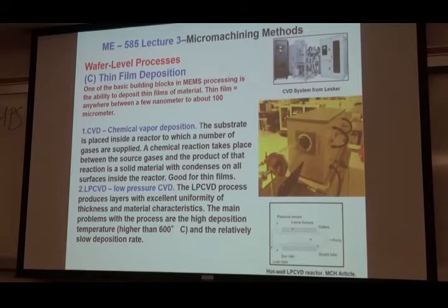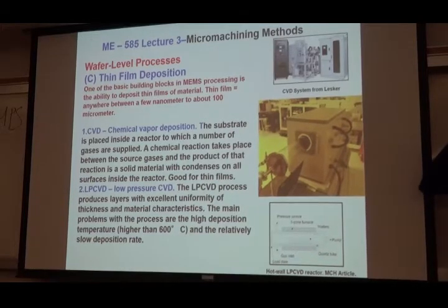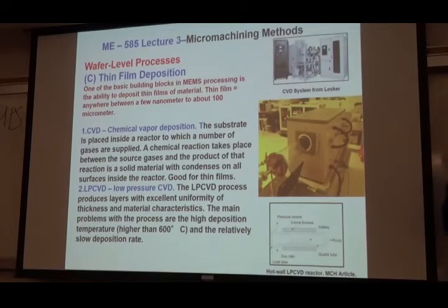Now, there's a material called graphene. That comes to that. So for the glassy carbon that we do, we don't use plasma enhancement and all that kind of stuff. But if you want to create graphene, which is supposed to be an awesome material, I mean, you could look it up. With graphene, then you have to use PECVD. Okay, so CVD, LPCVD, low pressure CVD, PECVD, plasma enhanced CVD. Okay. Now let's go back to the other ones. Any questions so far?